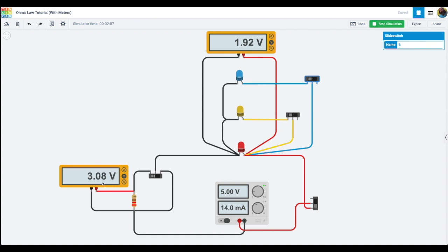And you'll also notice here, if I were to turn off this resistor, you'll see that they all have too much voltage, or current. See, the current through the LED is 483 milliamps, and the absolute maximum is 20 milliamps. And so you've got too much current going through there, and that's why it blows up. Same with this one, same with that one. And even if I turn these off, you'll see that all that current is still going through that one, and all of the voltage.